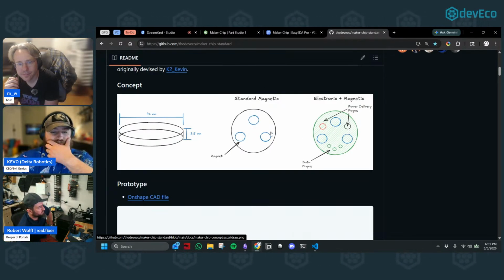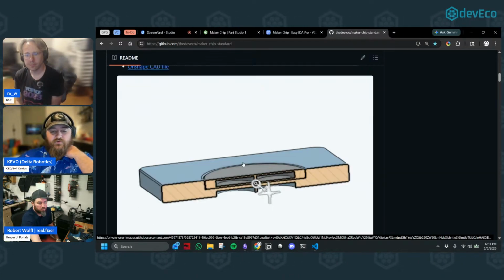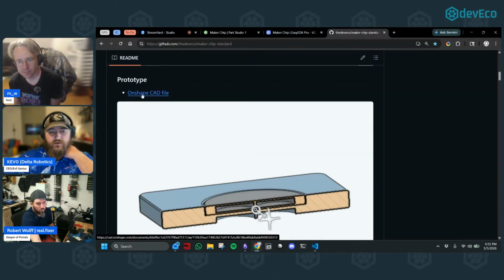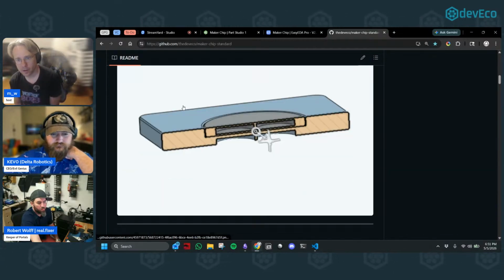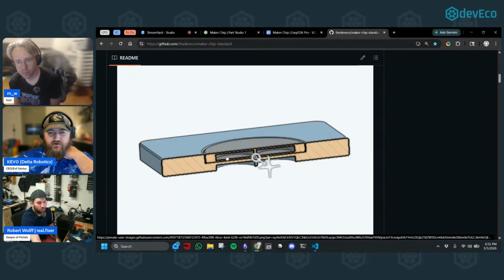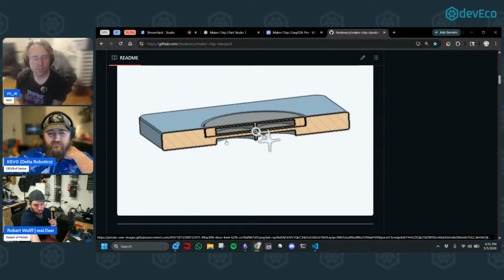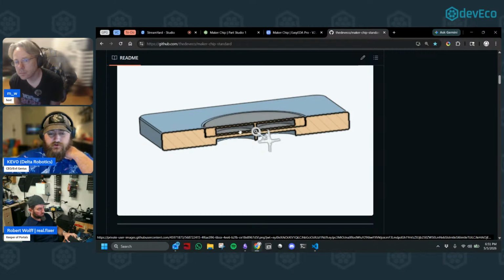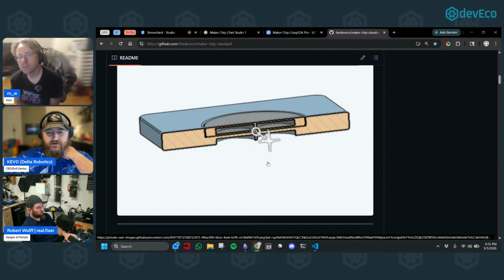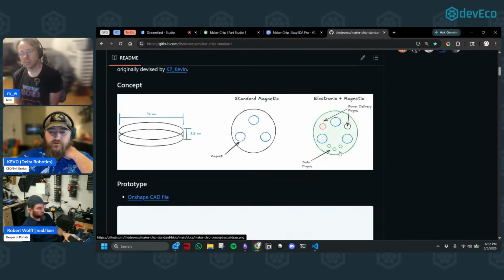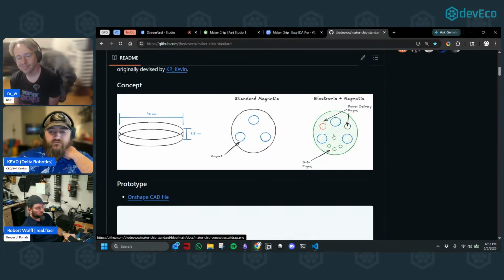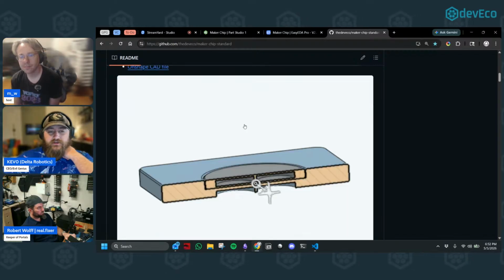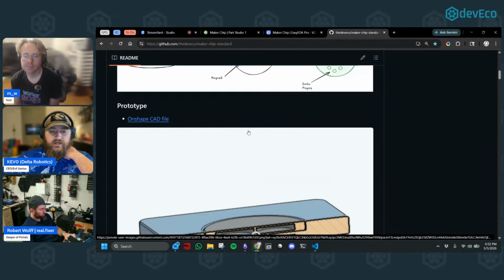And I wanted to upgrade on top of this. The original CAD file here, which this link will take you to the Onshape file, should be a public project. This was a very simple proof of concept. You have your magnet in the base, which is polarized, south, north, reversed, so that your magnet lands in the same direction every time. And this becomes important when you start adding pogo pins, data lines, information, because having the wrong pin connect to the wrong thing could be not so great.